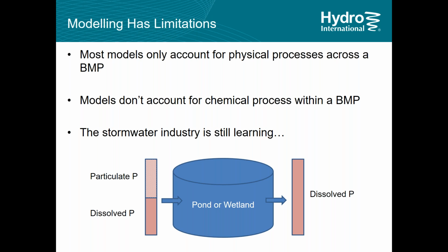But what they've done, some studies up there, and they're actually working out that a lot of these BMPs are actually doing conversion processes inside them, so that you get this mixture, like you get 100% of the phosphorus coming in. It's roughly a 50-50 split between dissolved and particulate. It goes into the BMP, and the same load's coming out the other end, and so what's going on?